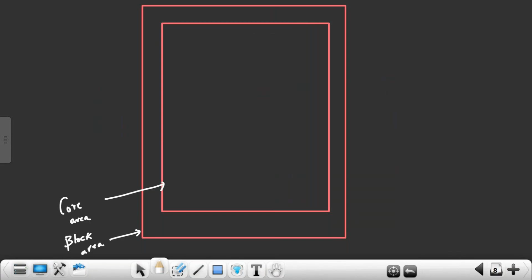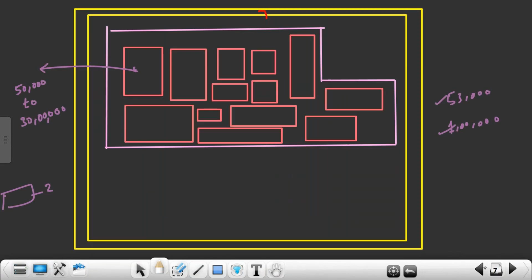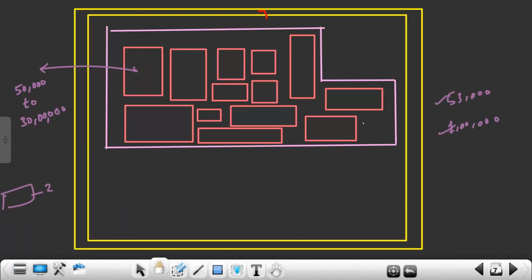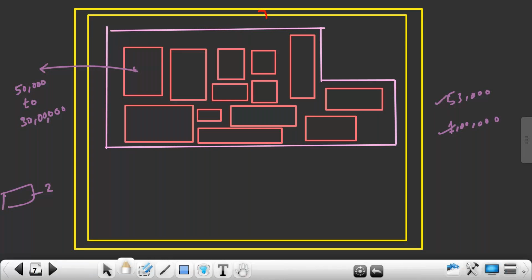So how to create this? What are the commands we have? Generally in the industry, this core area and die area will come from whom? The subsystem level lead. He will give it, because we can't decide. We can't make our block whatever size we want, because that block ultimately has to fit in his subsystem. So he will give us. In what format will he give us? If he is not giving, how do we plan it? At the beginning, in the industry, he may not give.